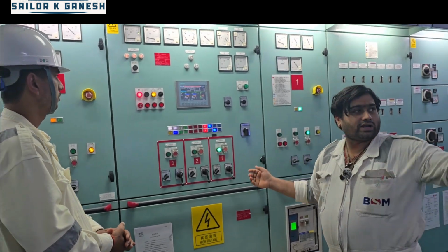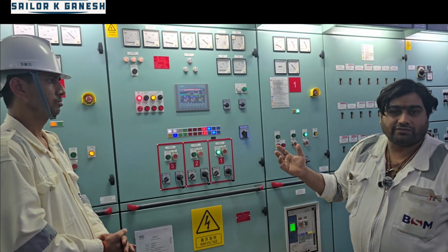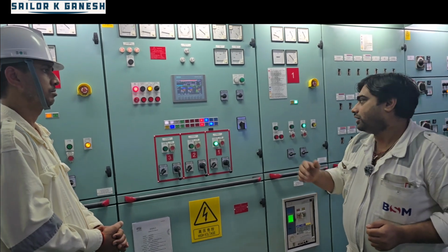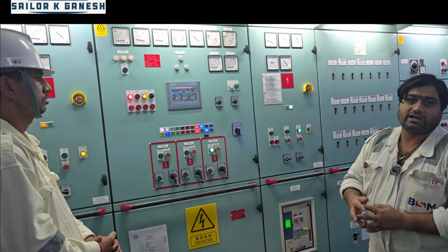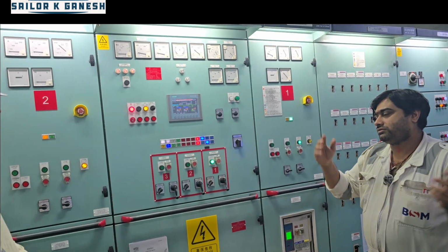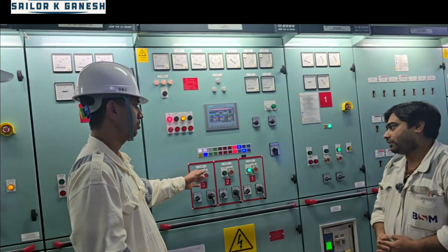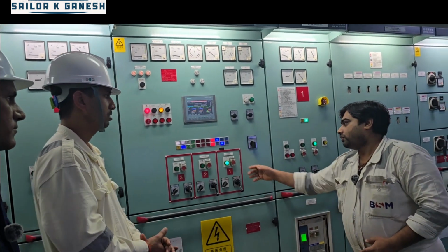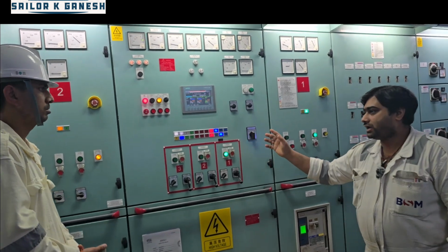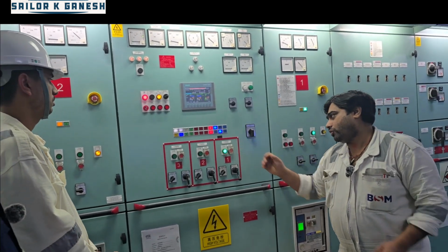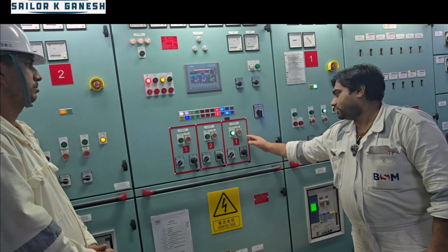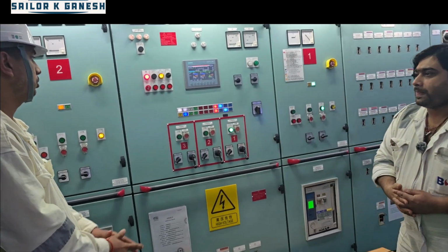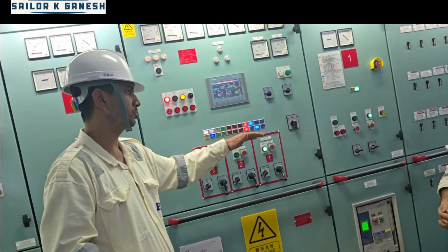For heavy loads, like running the power pack and other heavy consumers like the IG generator, you need another generator, and at that time you need to run 2 generators in parallel. And any time we require 3 generators, or are 2 generators sufficient for all the operations? No, usually for heavy loads like the IG generator and power pack you need 2 generators, but for normal running 1 generator is sufficient. So we never run all the generators together.